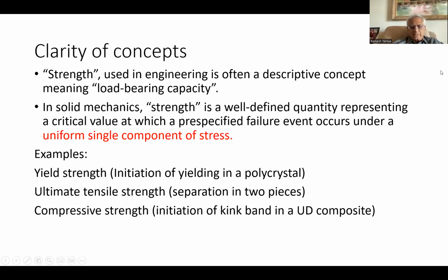The solid mechanics definition is quite precise, which is if I apply a single component of stress, the material responds to that by deforming, and at a certain point it reaches a pre-specified criticality. And the value of the stress associated with that is what we can call strength. Because it's well defined, it can also be measured with some standardization and regarded as a material property. Examples are clearly yield strength that we know from classical times, ultimate tensile strength, and so on.